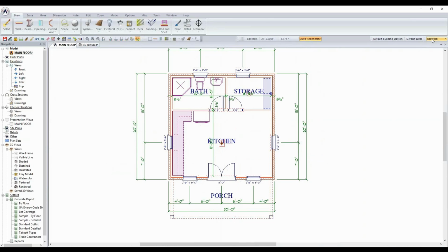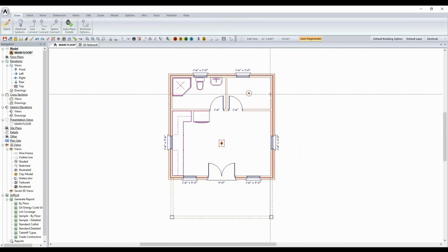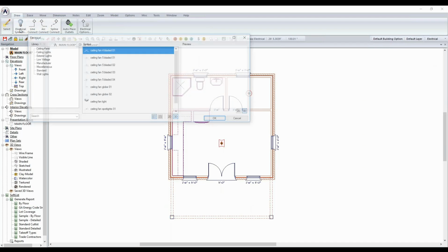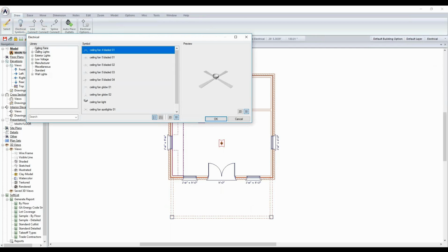And the only last piece is I wanted to show you electrical mode and the difference. So if you take a mental snapshot of that right now, this is electrical mode. So it's exactly the same drawing. We just turn on and off certain items so that they don't clutter the drawing up. So you're going to have all your notes for your floor systems and so on in there. It can turn those off so that you can easily come in here. And it also has a pared down list of commands that you can put in. So you can go to electrical symbols, and I can go to just say my standard list here, and I can find switch.